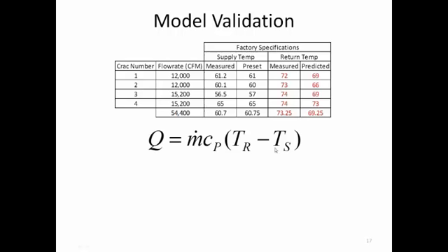So here I'm trying to validate. When I'm looking at, so you measured the supply temperature. That's correct. And you used those values as boundary conditions. Exactly correct. And then use the factory flow rates, right? That's right. And this is most typically what I do: if it's an existing data center, I will just put a probe down on the floor and measure the supply temps. It's the quickest way to calibrate or to validate the model and to correlate the model.